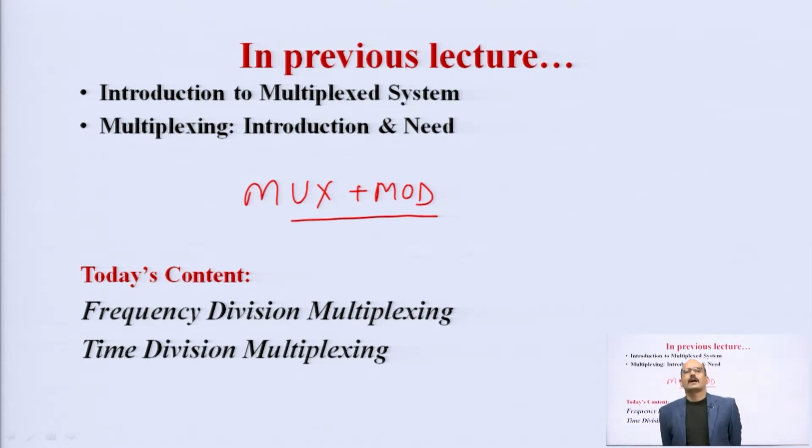As the data coming from the sensors is of low voltage, that voltage has to be increased at the transmitter side. Also, the frequency of that signal is very low, and to send that low frequency signal to a distant place we require modulation.